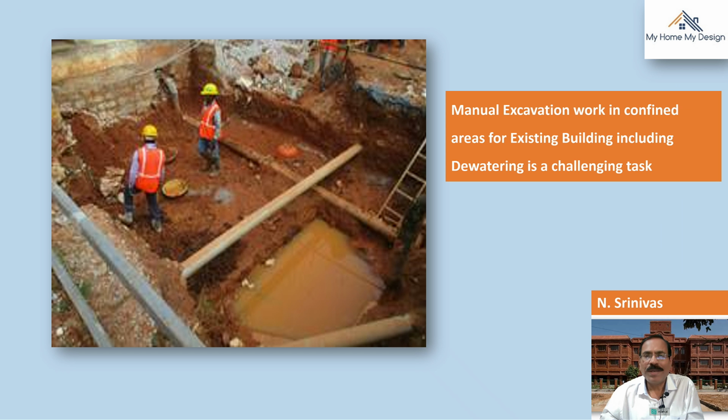See here, manual excavation work in confined areas for an existing building, including dewatering, is a challenging task. Of course, see here, a lot of pipes are coming through. If you touch them during the excavation process, there is a chance of these pipes bursting, and there may be a chance of more water coming into the excavated trenches. In order to avoid all those things, care has to be taken depending upon the site conditions.